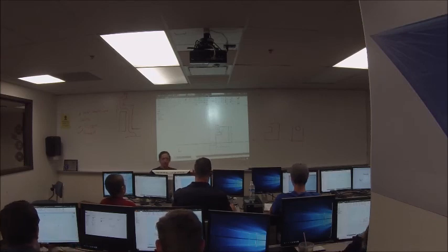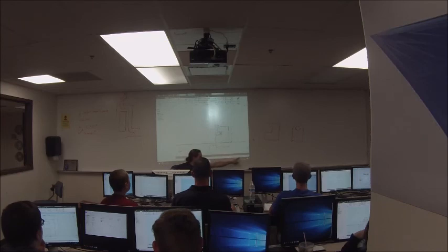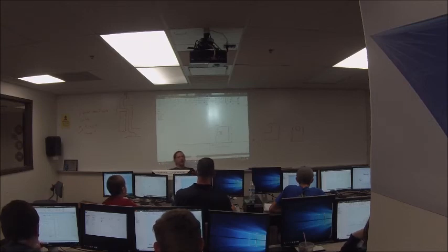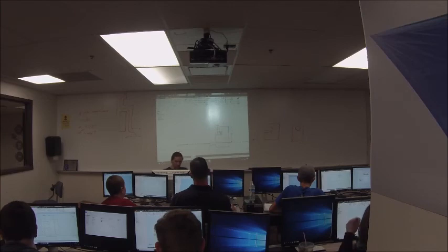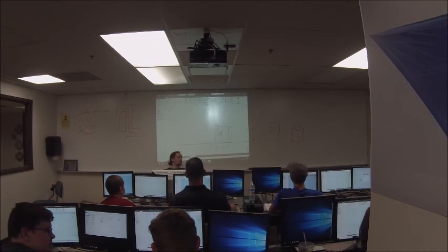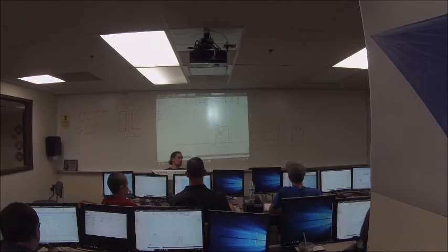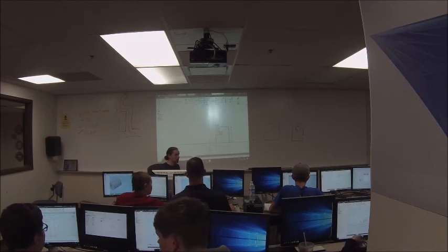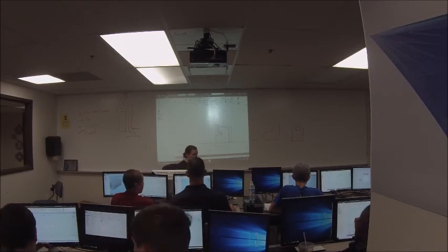How do you tell if it's fully constrained? Down here in the corner, does it say fully constrained? That is fully constrained. I've never had it say fully constrained when it wasn't, but I have had it say it wasn't fully constrained when it was, but only with really complicated sketches. Does it say it's fully constrained down in the corner? Well, you can just start clicking and dragging and see what moves. If it moves, it's not constrained.